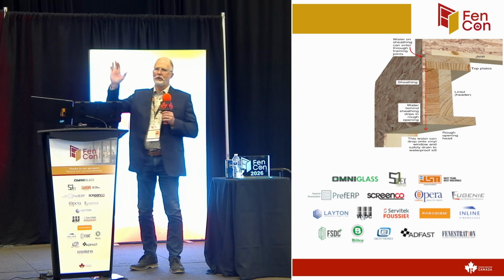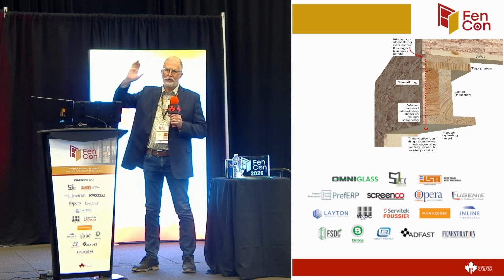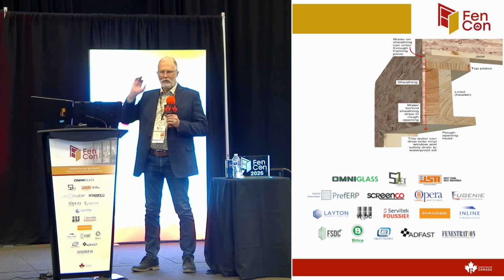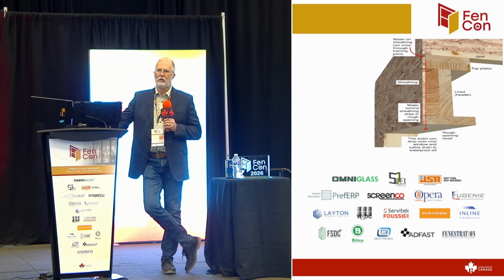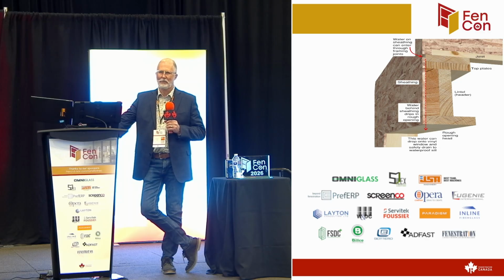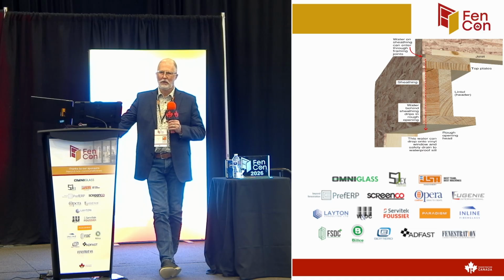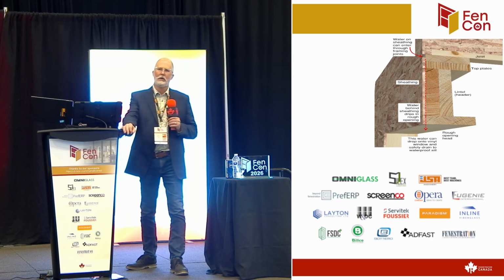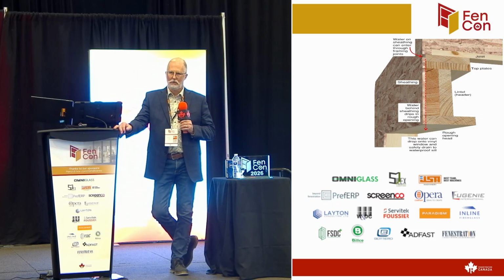So are you thinking 4-side seal is a better approach? It's just another approach. Anytime you get into a new technology, you're in the Wild West where there's going to be problems you have to solve. There are issues with that, of course, that you're trying to overcome. I feel like 3-sided seal might be a bit of admitting defeat to failure. It might work in residential where, of course, you've got Wild West installations, but say commercial where you have outboard insulation and a lot more stringent requirements to keep that out, where your AVB is sort of one plenum with exterior outboard insulation, then potentially there's some benefits there.